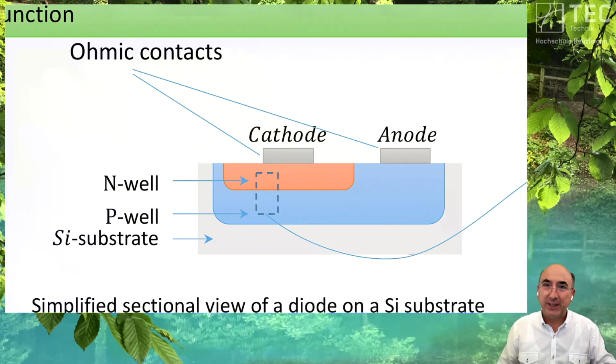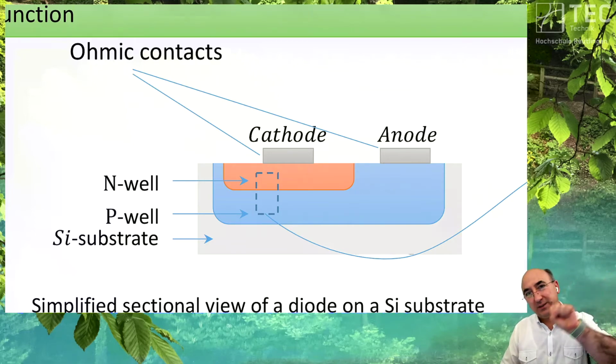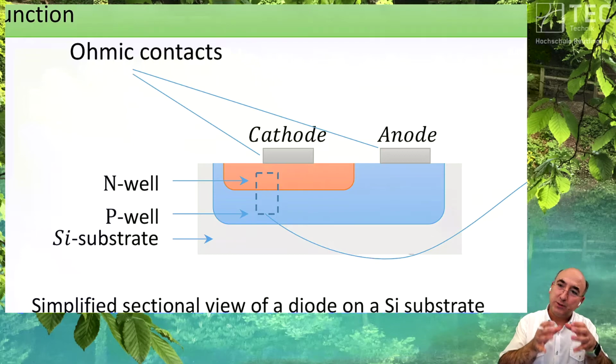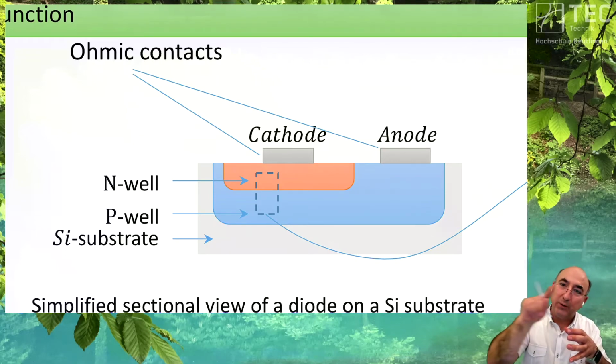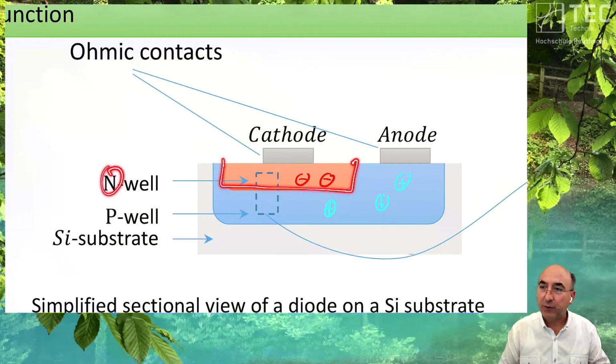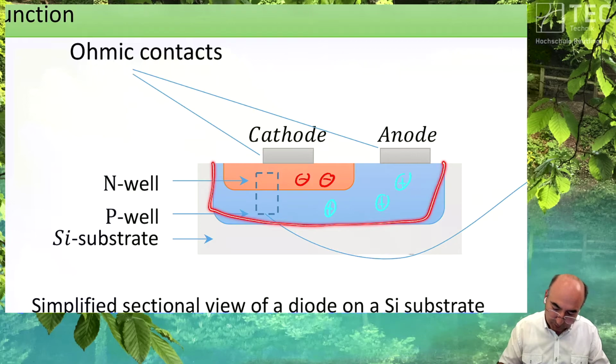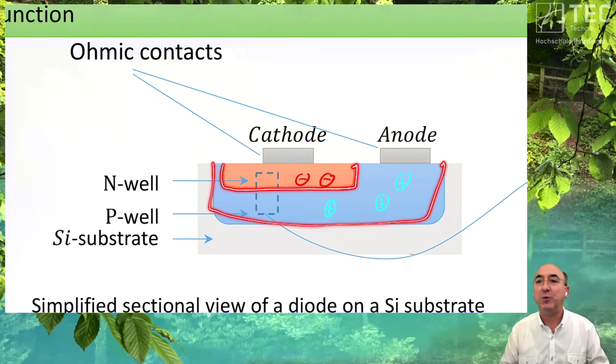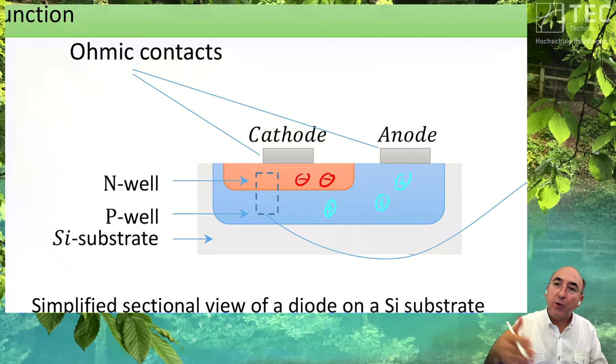Boron, right. Boron has 3 valence electrons, and you need 4, so it takes away from the lattice 1 electron. It's bound to the lattice, so it's negatively charged. Space charge is negative, and it generates a hole, and this hole is movable. Okay, so we have here movable holes. And we have here movable, no, not plus, movable electrons. So the n-type doped area is phosphorus. Yeah, so we have a p-type doped area, and within this area, we have an n-type doped area. And this happens by overdoping the p-type. You can remember?